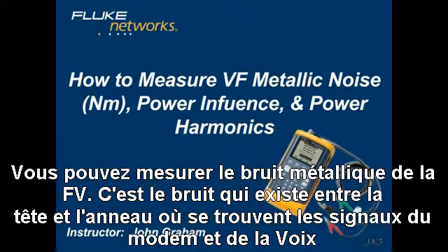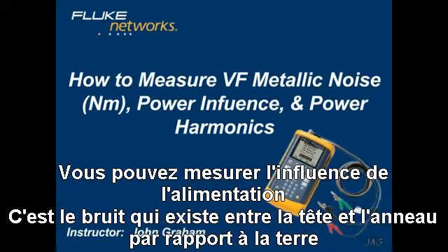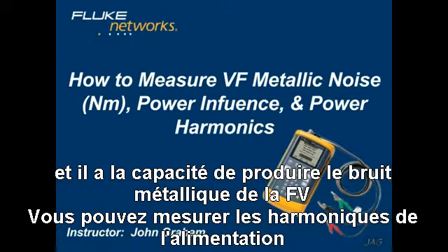You can measure VF metallic noise. This is the noise that exists between tip and ring where the voice and modem signals are. You can measure power influence. This is the noise that exists between tip or ring reference to ground, and it has the capability of producing VF metallic noise. You can measure power harmonics.